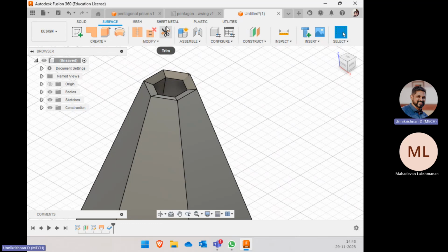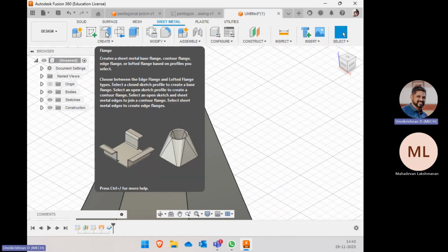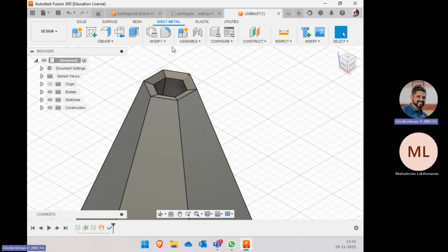I know you are asking for that, but when I drew the cone, I drew a line, then came to the flange, made a very small thin profile of 0.001 mm, and then only I came to the thickening part of it, and then clicked the join.